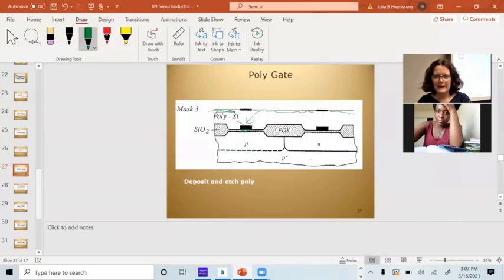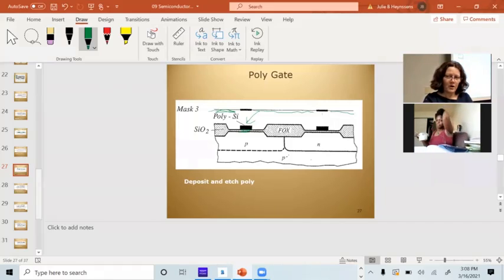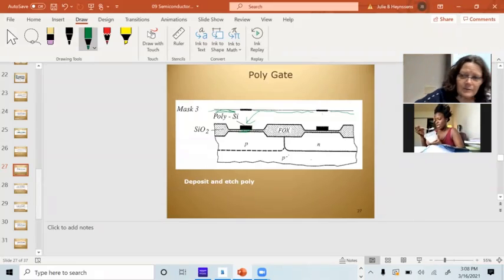Okay, now we're going to talk about Micron for a minute here. Micron is one of the few places that makes their own masks. And if you think about it, if you have a 9 nanometer process, your masks have to be exact and perfect at a level smaller than 9 nanometers. Because if my feature's 9 nanometers, I can't have 9 nanometer imperfections in them. And the masks have to be perfect.